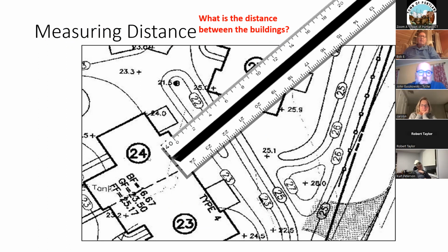So what we're looking at here is a site plan with several buildings and a multifamily layout. So we have house 23, house 24, which are duplex, and across the way from another house, maybe house 25. This is drawn at 40 scale. So you see that we're using the right distance here. We're using the 40 edge of the scale. So about how far distance are these 2 buildings? What's the gap in between the 2 buildings across the way?